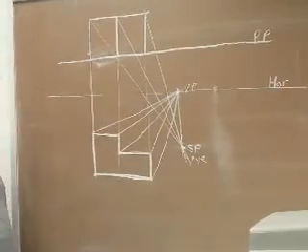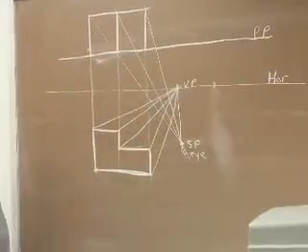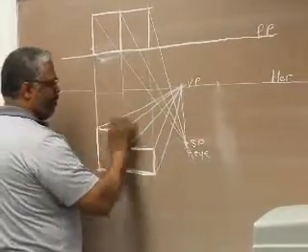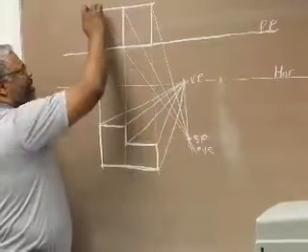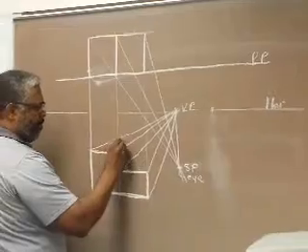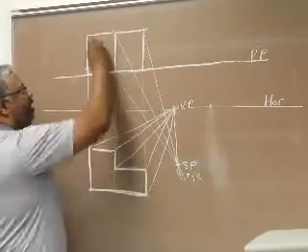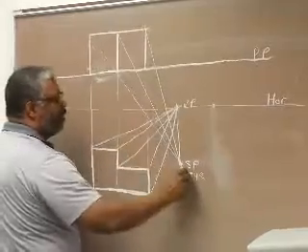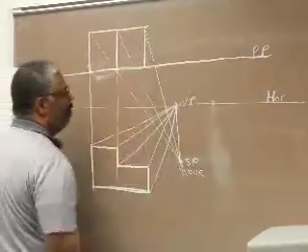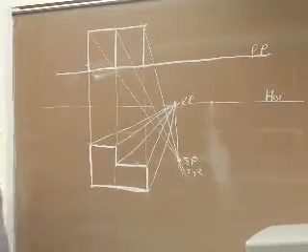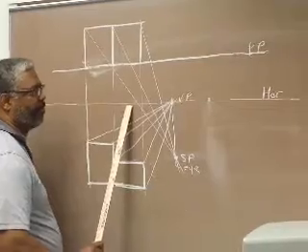So now we have lines here to show depth going back to our vanishing point, and we have to get the depth of wherever, how far, what's that distance from here to here, and we do that by taking lines from my station point here, or lines from my object going to our station point, where those lines cross the picture plane. Now sometimes students have it crossing the horizon.